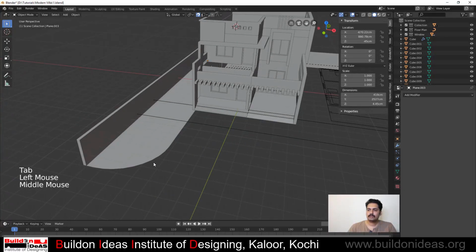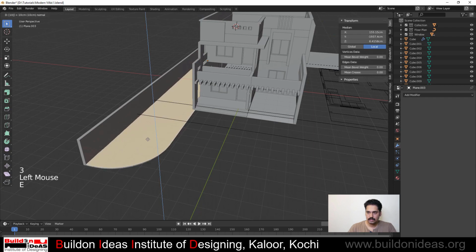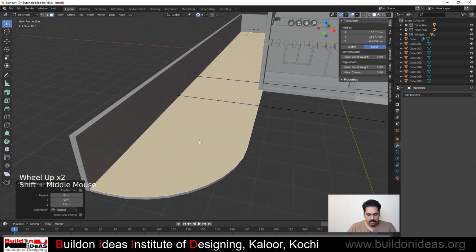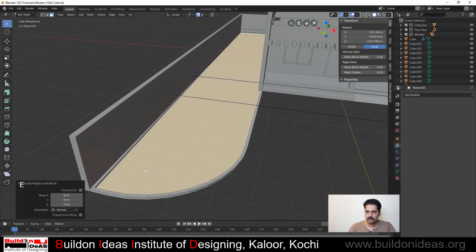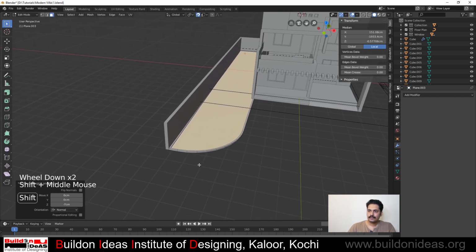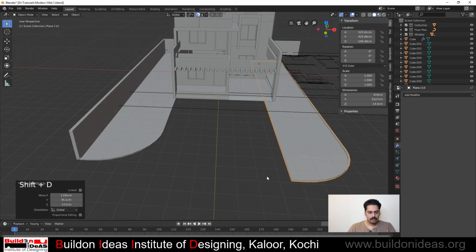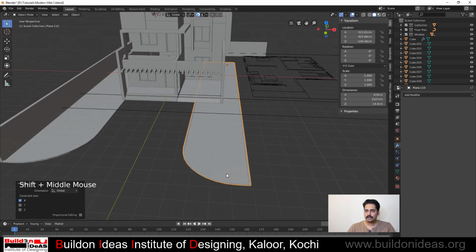This is how it is, and then you do an extrude 3 face, and then extrude to 10 centimeters. Then you will just insert it into say 10 centimeters. Once again extrude it to minus 7 centimeters. So you have it. Give Shift D, and then you want to mirror it. So Control M gives the mirror, and then just in X direction you have it.